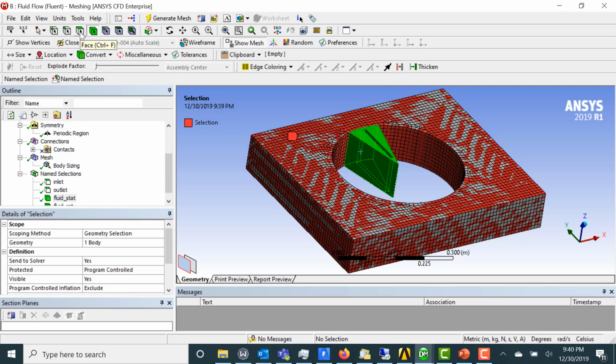The requirement for the mixing plane is the interface between the 360-degree surface and the 30-degree surface. These should not be defined as interfaces. They have to be pressure inlets and outlets in order to be identifiable by Fluent as candidates for setting up a mixing plane.